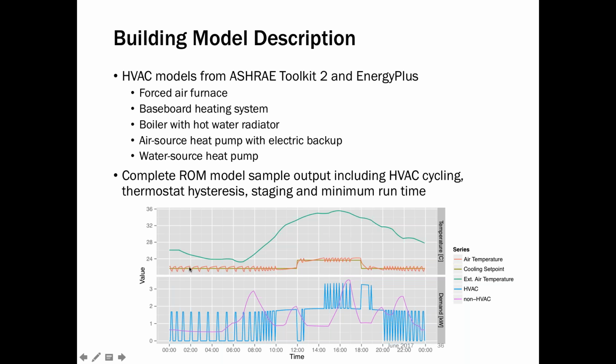You can see the cycling of the central air conditioning system in the home over the course of the day. The cycling coincides with the compressor on time. The compressor operates more and more frequently until stage 1 is continuously on. Then people go to work, reset their set points, but soon after stage 1 is not enough and stage 2 starts to cycle. Things get worse in the evening when people come home and reduce the set point. Now you have the hottest conditions and the highest load. Both compressor stages are running.